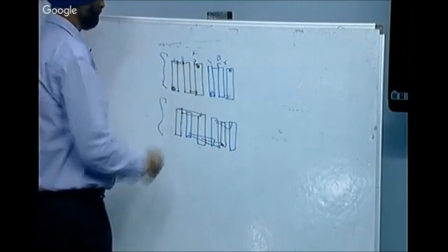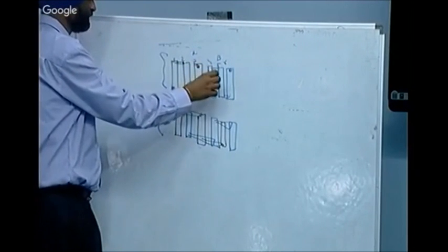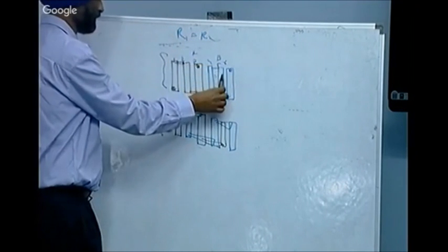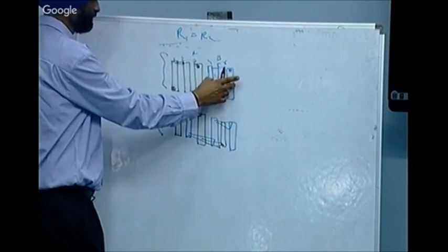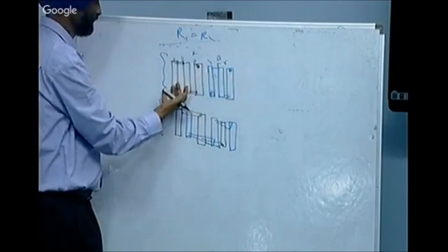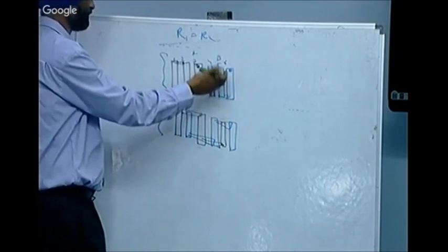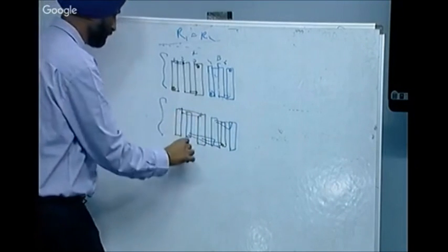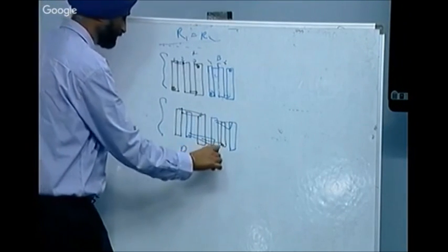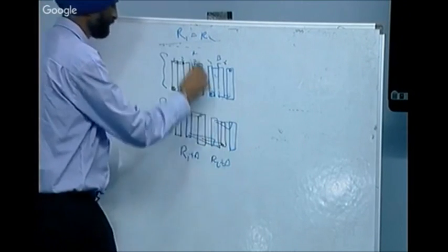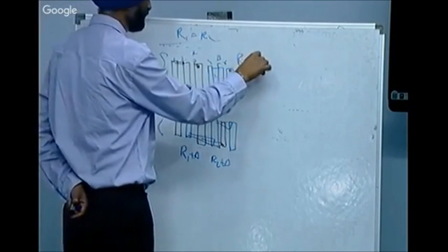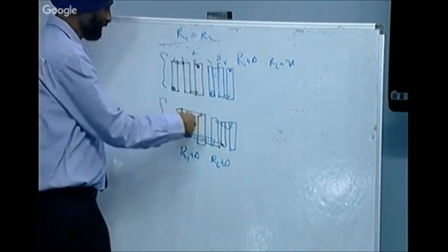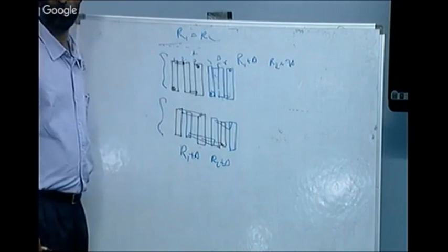Like this one, if there is a gradient, this resistor though you wanted R1 to be equal to R2, but here most of the gradient will, here it's more, here it's less. It has taken all the gradient here, so this resistor will be different. Here the gradient is uniformly distributed because this will be R1 plus delta and this also will be R2 plus same delta. In this case, it is R1 plus delta and this is R2 plus some 3 delta. So this kind of differences will be there. But here connections are becoming more